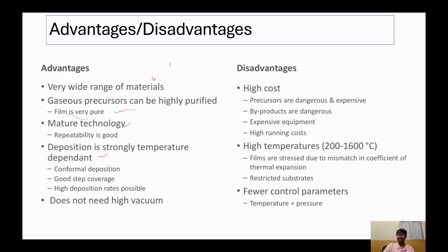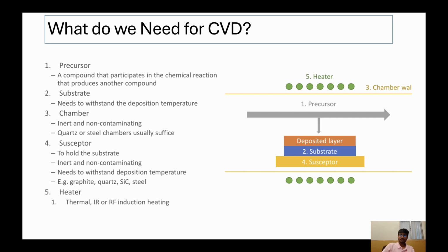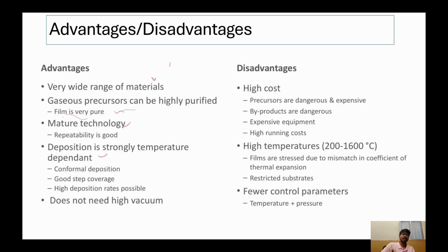The main part is the reaction, because at higher temperatures the reaction kinetics gets changed, and that's why. And also good step coverage you can get, because the gases can go everywhere. High deposition rates are possible at higher temperatures.